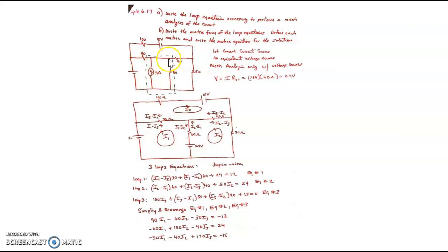The 60 ohm, it is parallel because this terminal is connected parallel to that terminal, and that is connected parallel to that terminal, and there is nothing in between. So this is a perfect combination for us to make the transformation. So let's do that. Let's find the voltage equivalent using Ohm's law. So I get 24 volts. I have 0.4 amps times 60. I get 24.